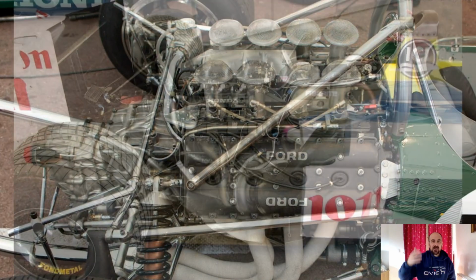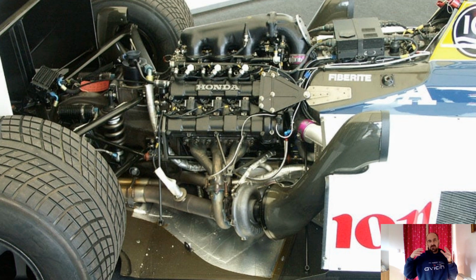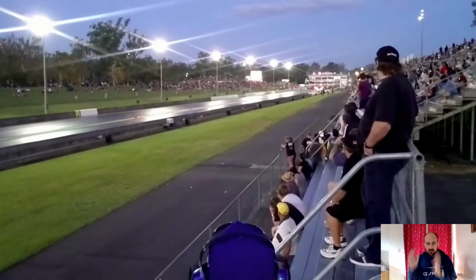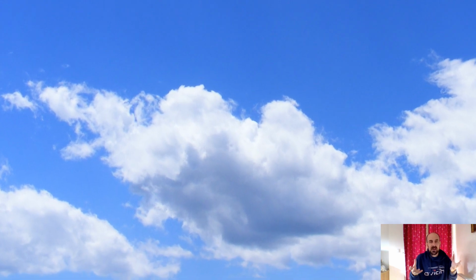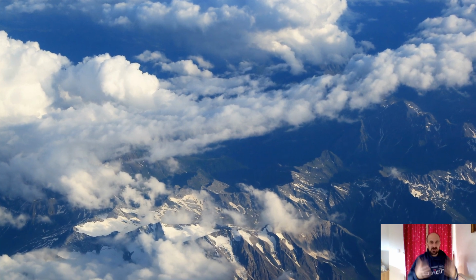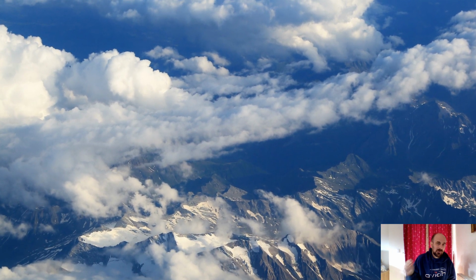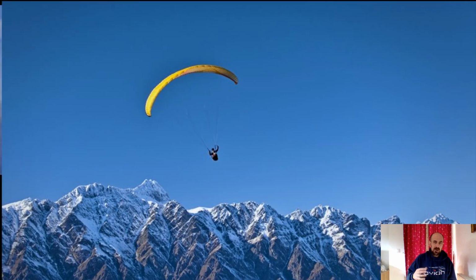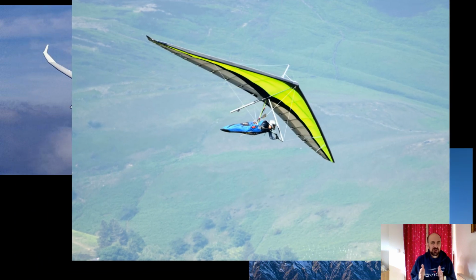Now in a lot of areas, for instance think of cars, when we talk about performance, you can improve it by increasing the power. You burn more fuel, you use more energy, and it makes you go faster. That doesn't work with gliders. With gliders, we have a fixed energy source, which is the amount of energy in the air on any given day. So when we talk about performance, we're talking about efficiency, getting the most out of the smallest amount. In the context of a glider, efficiency means lift to drag ratio.